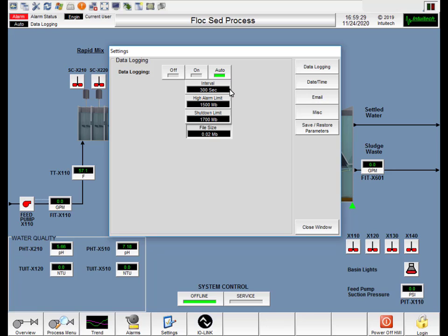The less often used way requires you to power down the HMI before you remove it from the front panel. Then you physically remove the USB. The second way, which is the more commonly used way, is to retrieve the data using remote connection to the HMI, using Ultra VNC and then downloading the files.